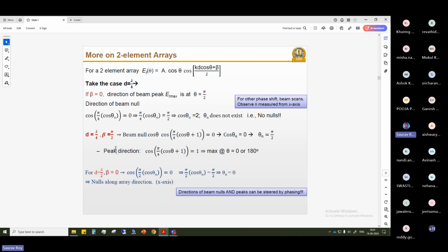But this is one thing; we are just talking about the antenna pattern. If you look in depth, there will be other terms, like S11, and the mutual interference is also there. Generally, if you take the distance between them less than lambda by 2, the mutual interference greatly increases.